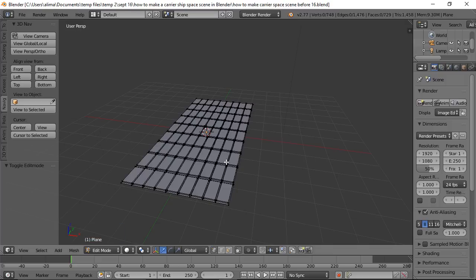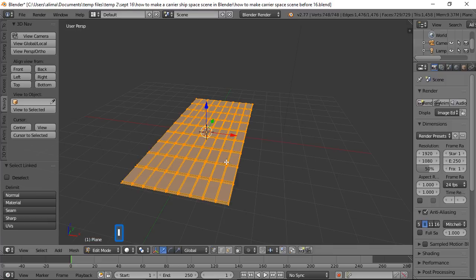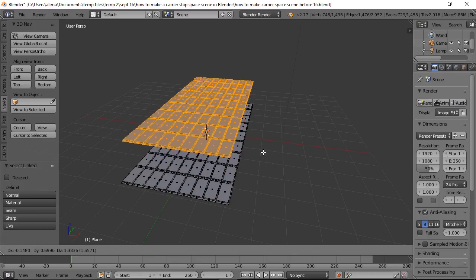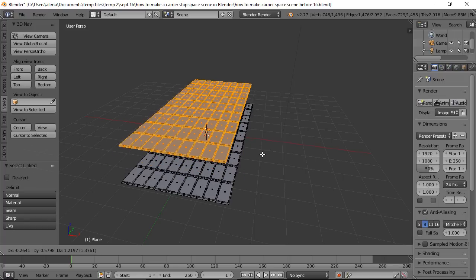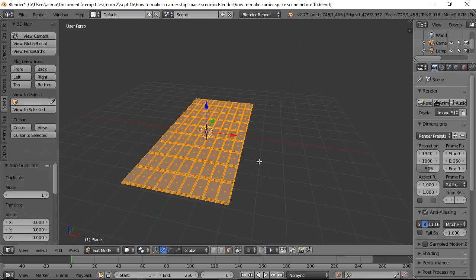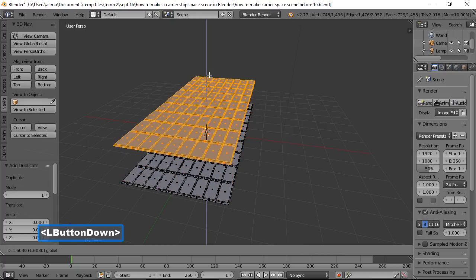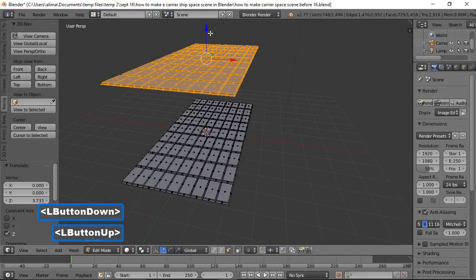Okay, so now we have all this detail. So we're going to press L. So I hovered over here, I pressed L. When I pressed L, I was able to grab all of this geometry right here. Currently we're on vertex select. I'm going to click here to go to face select. I'm going to hold down Shift, and then while holding Shift press D. That duplicated that geometry. Typically when I duplicate things, I'll wiggle my mouse just because I want to make sure that I have the geometry duplicated. I'm going to right click to get that geometry to jump right back into place. I'm going to take this manipulator to move that duplicated geometry up to about here.